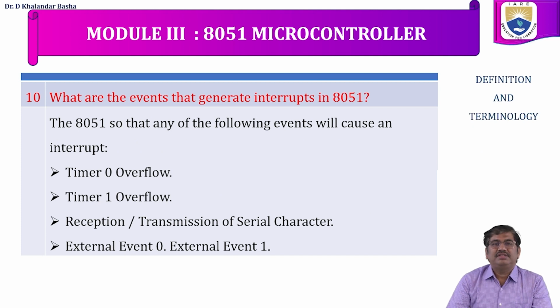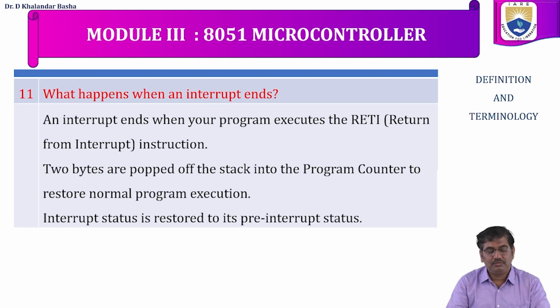What are the events that generate interrupts in 8051 microcontroller? The 8051 has the following events that can cause an interrupt: timer 0 overflow, timer 1 overflow, receiving or transmission of the serial character through the serial port, external interrupt 0 and external interrupt 1.